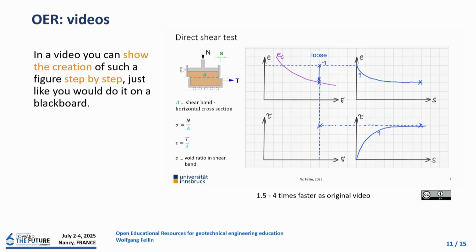You can repeat this with a sample with a lower stress level. You can highlight where the action goes, and then you will end up with the construction of a second point, and then you can construct a straight line, which is the shear stress line of the critical state, which is inclined by the critical friction angle.